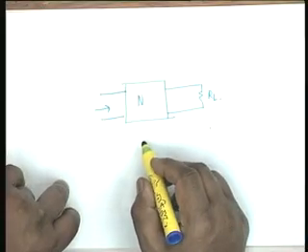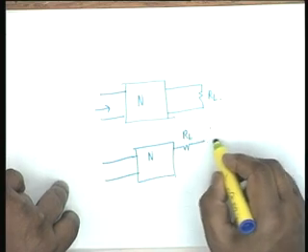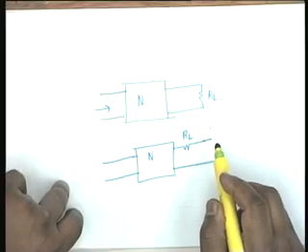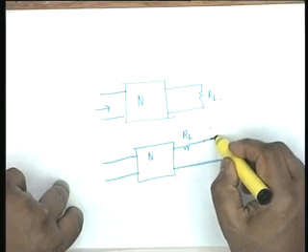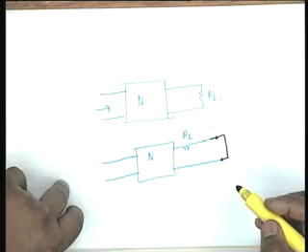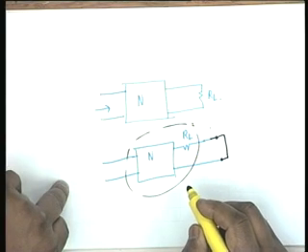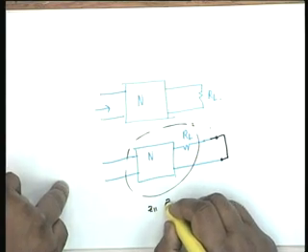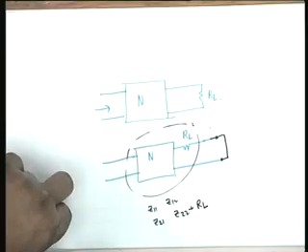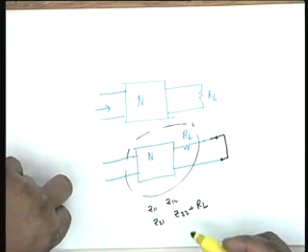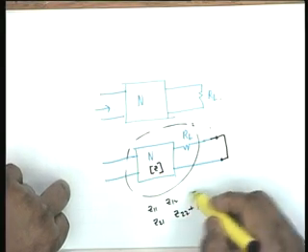We find in terms of parameters, then we make substitutions. All right, I can look up on this network. Be careful now what I am doing. No tricks, very simple method. I can look up on this network as an augmented one with an RL at the port number 2, okay, and then the output port is short circuited. Is that okay? Yes, all right. So this network, what are the Z parameters of this network? Z11, Z12, Z21. The only thing that happens is Z22 is augmented by RL. Agree? The Z parameters of this black circled network, Z parameters of N are given by the Z matrix, and the Z parameters of this is this.